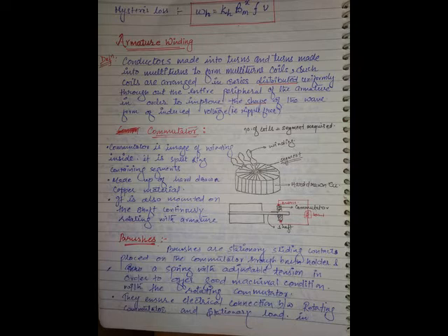If you have 10 conductors in series, each conductor is cutting the flux, and in each conductor 1 volt is induced. What is the total voltage? 10 volts. Like that, what is the voltage across these two? 10 volts. Don't think the voltage is 0. Don't divide them. Don't isolate them. Those two coils all are in series. Now, let us consider these are all the conductors in series. So, you can place these two brushes in this location, or in this location, or in this location.